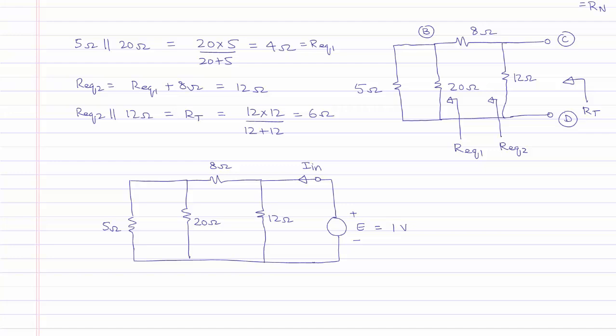We will use nodal analysis, select a node as the reference node. There are two other nodes, P and Q, at which we have to calculate the nodal voltages. Node Q is connected to a grounded voltage source, and we can write down the nodal voltage VQ is equal to 1 volt. And we do not write a KCL at this node.